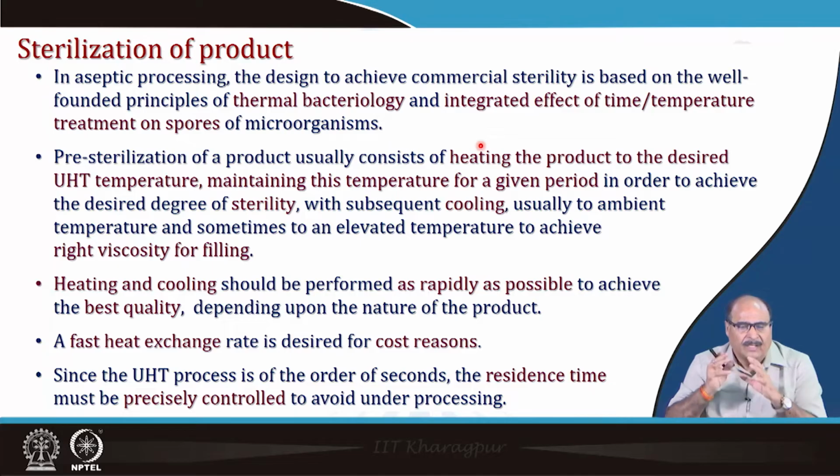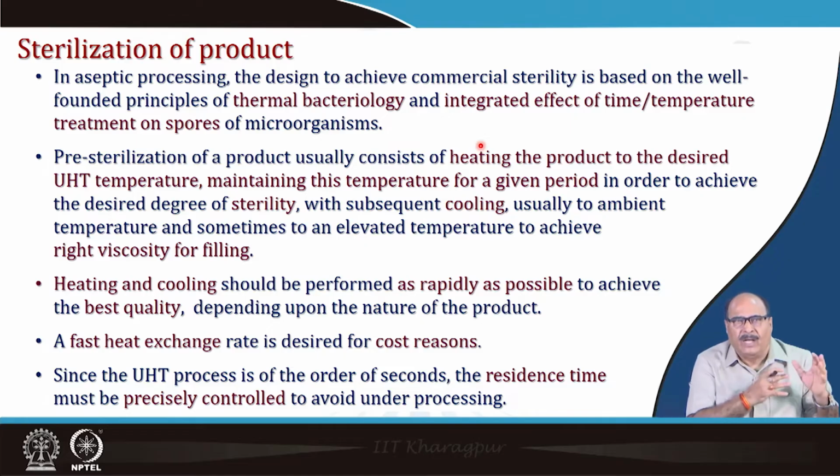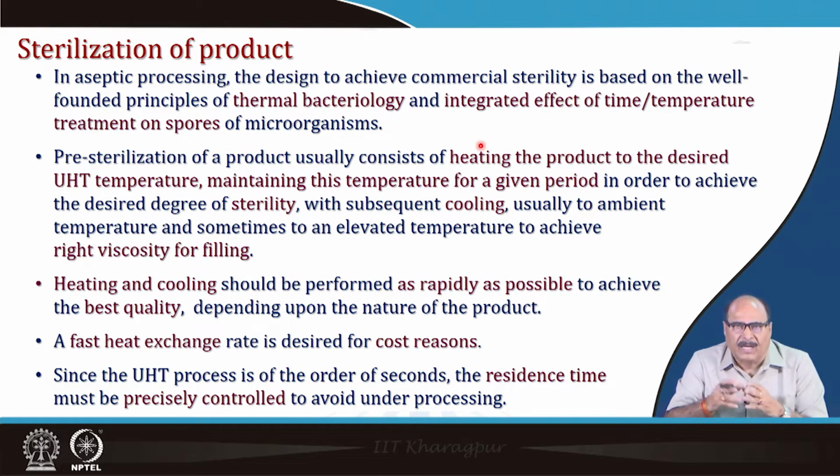Then the sterilization of the product in aseptic processing is designed to achieve commercial sterility, and this is based on the well established principles of thermal bacteriology and the integrated effect of the time and temperature treatment on the spores of the microorganisms or enzymes, as the case may be, depending upon the material being sterilized.